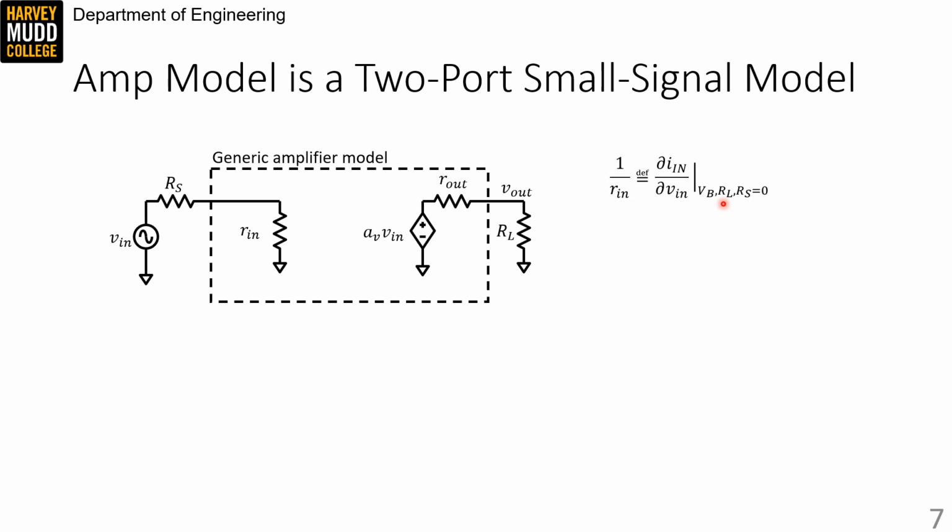Finally, we want Rs to be 0 when we're taking this measurement, so that we're only measuring Rin, right, and not some other series resistance that's added to it. That's a nice ideal, but in practice, we're probably going to add some series Rs to use as a sense resistor because measuring voltages is easier than measuring currents. So it's fine to have a little bit of Rs that you just subtract off of your Rin, or to think of the input as a voltage divider.